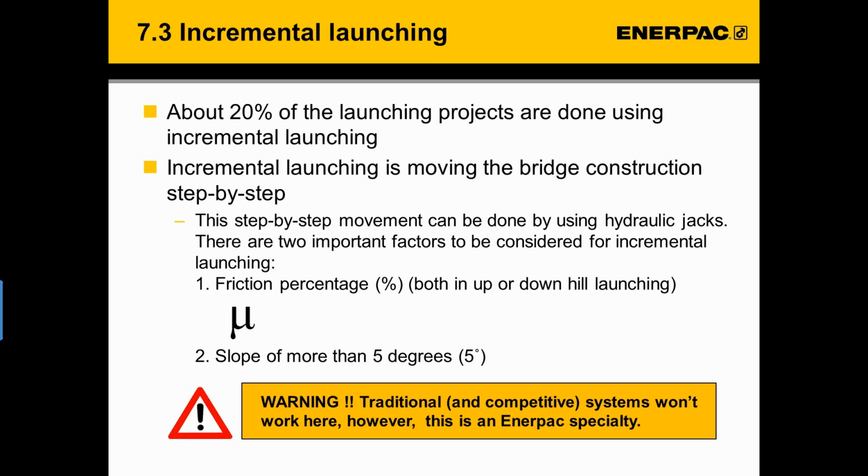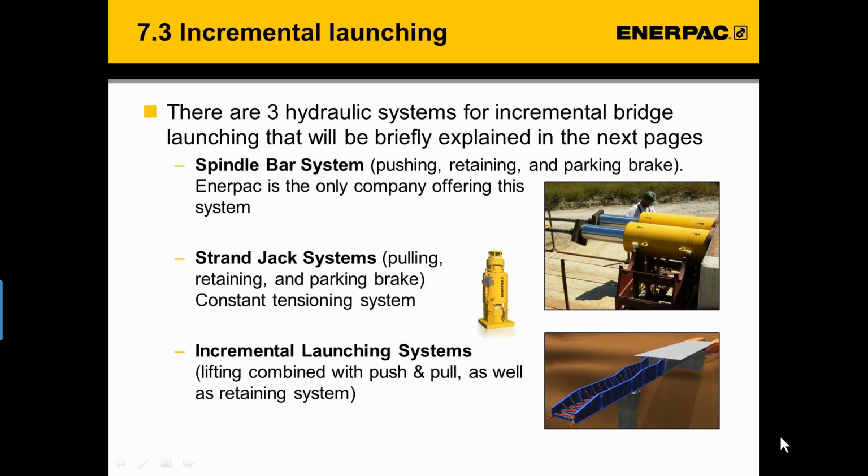The good news is that Enerpac is a specialist in controlled high-pressure hydraulics, especially designed for incremental launching in bridge construction, as we will make clear in the following pages. When talking about incremental bridge launching, we will discuss three different systems. The spindle bar system, unique for Enerpac, which is used for pushing, retaining and as parking brake.